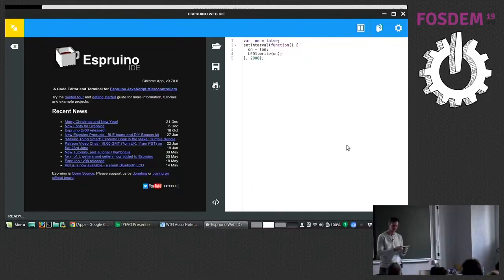So I did a little work with them when I was working at Vodafone. And here it is. This one, as I said before, you plug it in, it becomes a mass storage device. There's an HTML file in there. Click onto the link, and then you write your code in the actual web interface, and then you get a binary downloaded and it works. And there's a whole bunch of embedded controllers that actually use this. So you just pick the one you want, flash it down there.